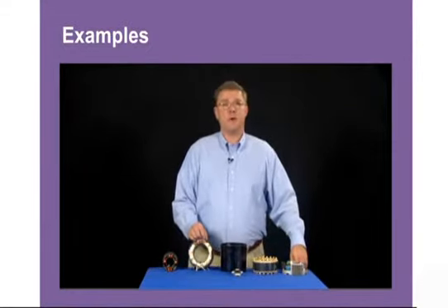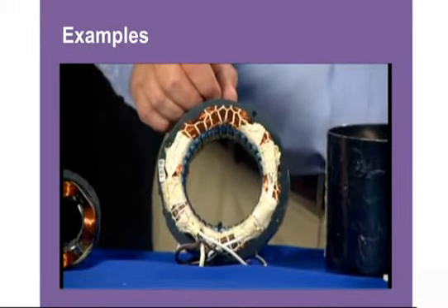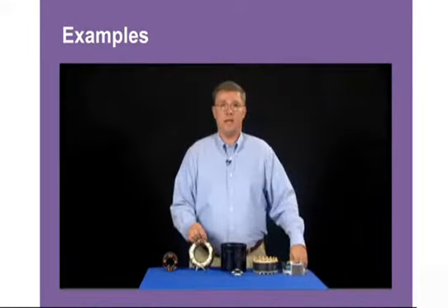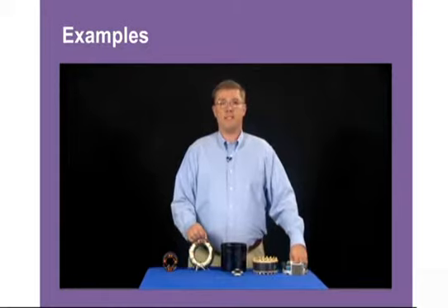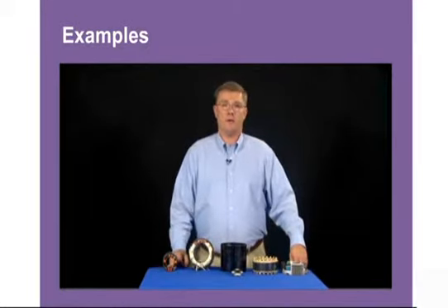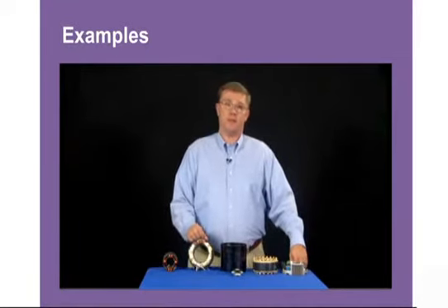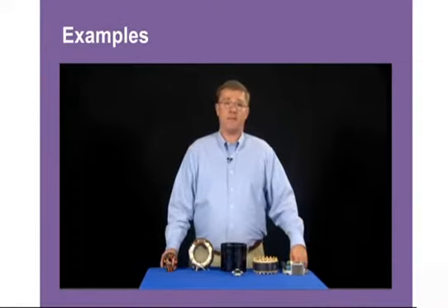The next type is a permanent split capacitor motor or PSC. This type of motor has 2 sets of windings, an auxiliary start winding and a run winding, and both windings are always in the circuit. Thus, this motor becomes twice as efficient as a shaded pole motor. Anytime it's possible to take a shaded pole motor out and replace it with a PSC, you should try and do it. How we do that is, a 6 amp motor that's shaded pole, we cut the amps in half and replace it with a 3 amp PSC.